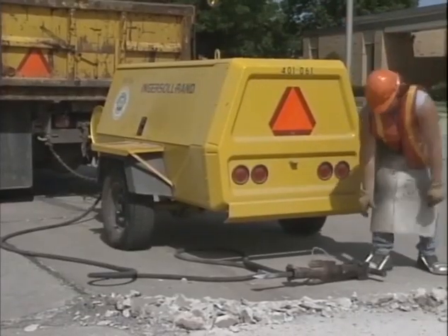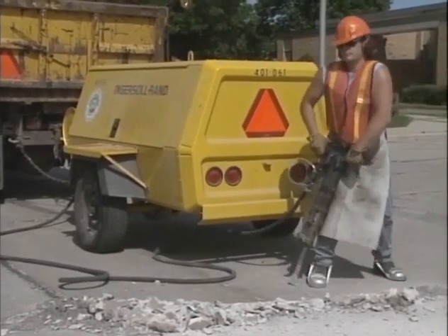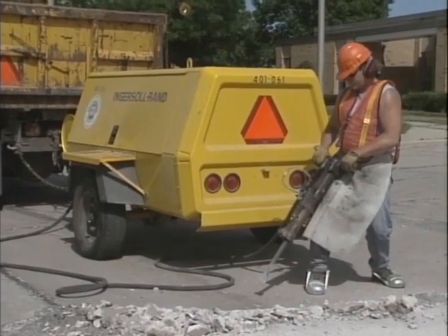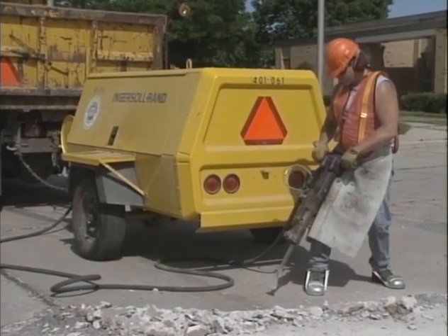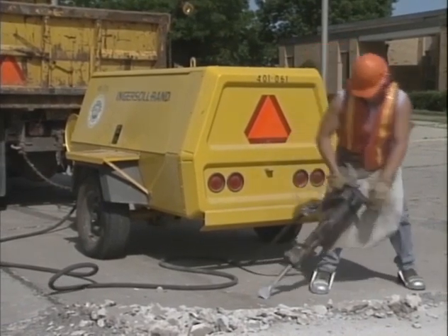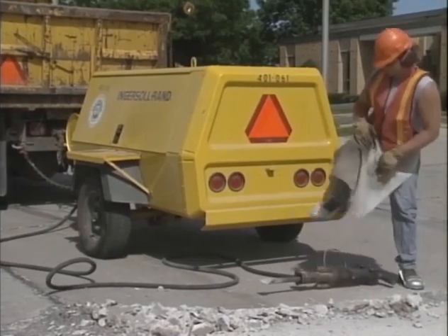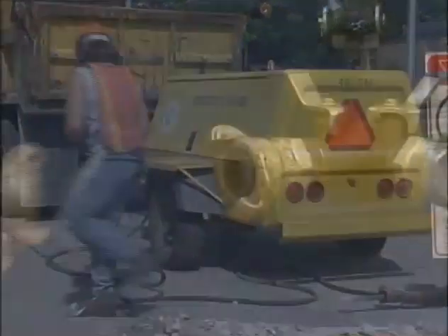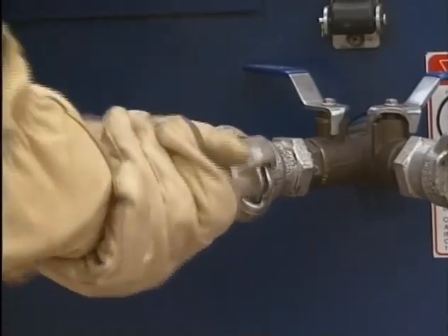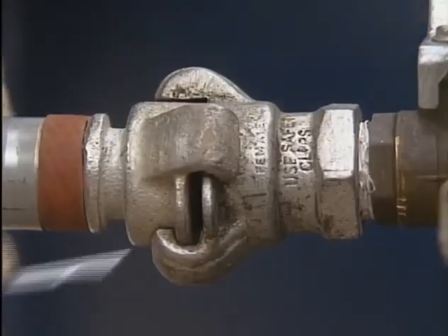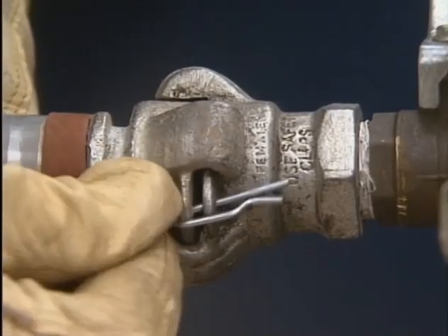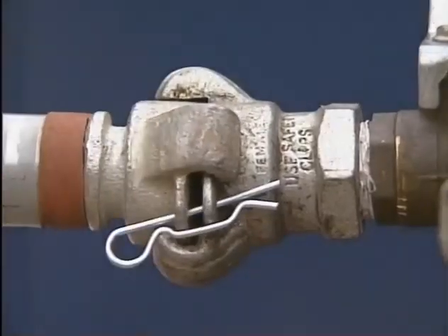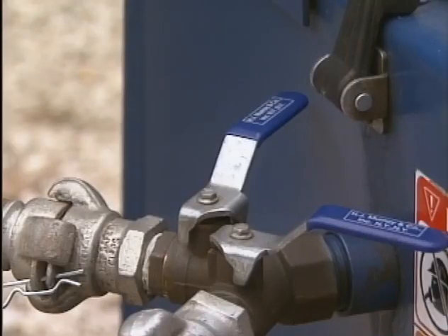Vent all internal pressure prior to opening any air line, fitting, hose, valve, drain plug, connector, oil filler, filler caps, etc., and before refilling anti-icer systems. Make certain all hoses, shutoff valves, flow limiting valves, and other attachments are connected according to the manufacturer's instructions. If the air compressor is to be used in conjunction with other sources of air, be certain there is a check valve installed at the service valve.